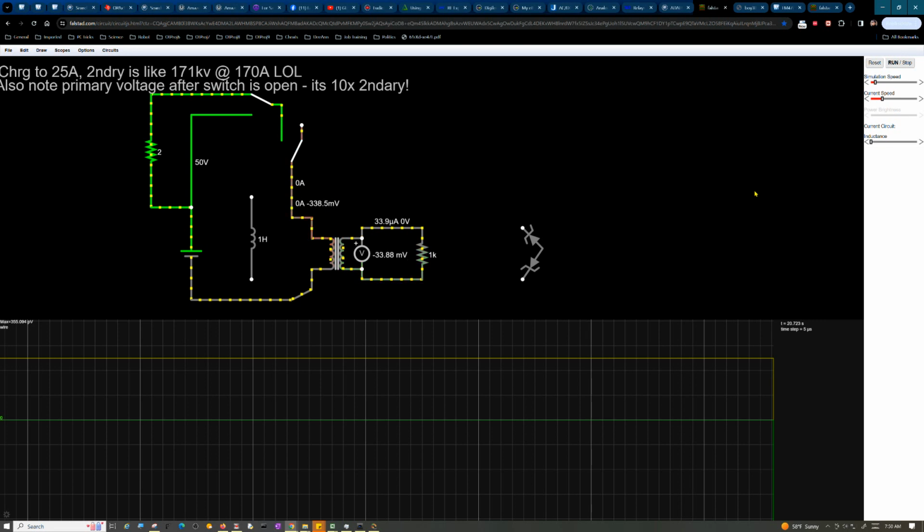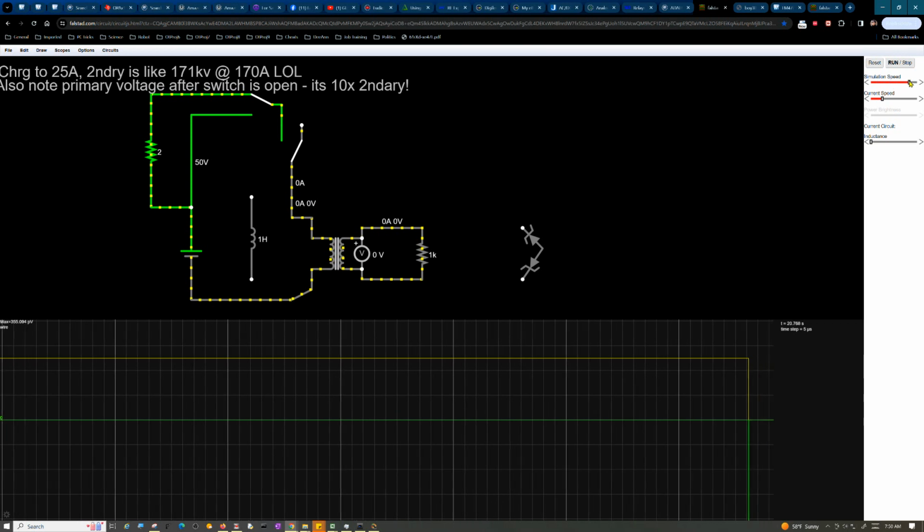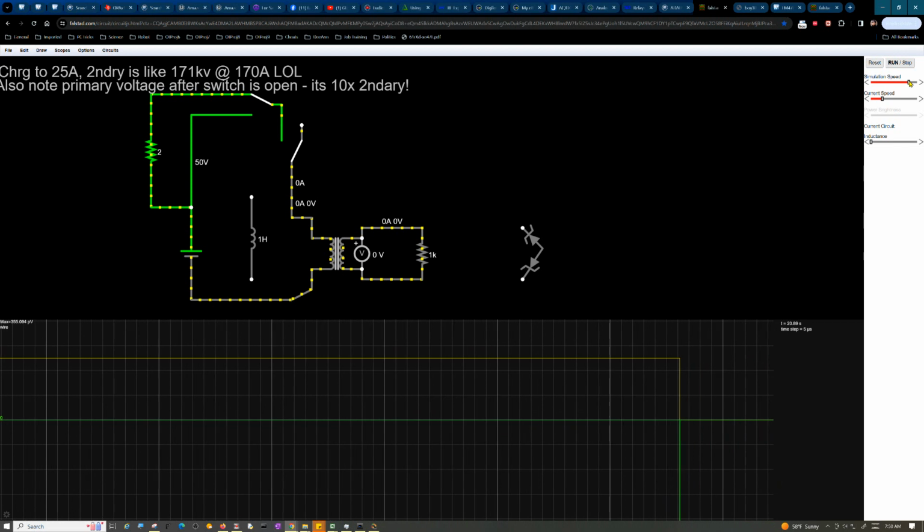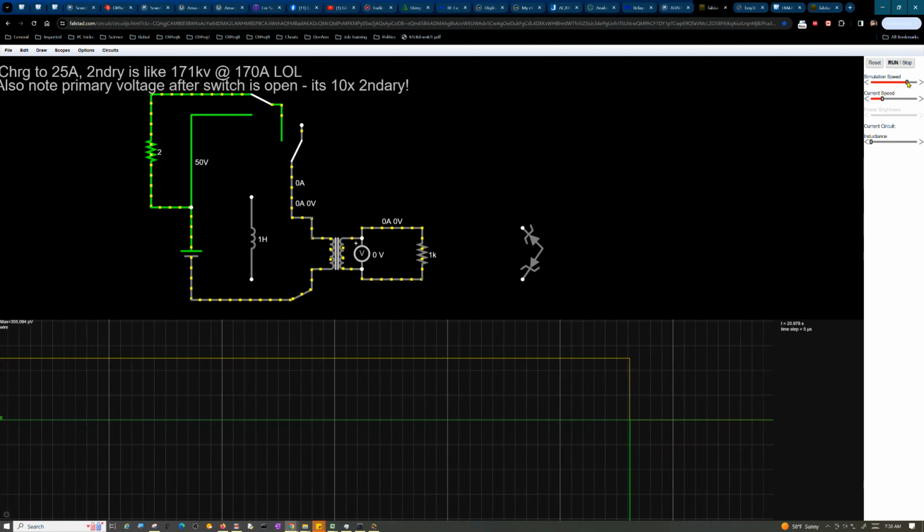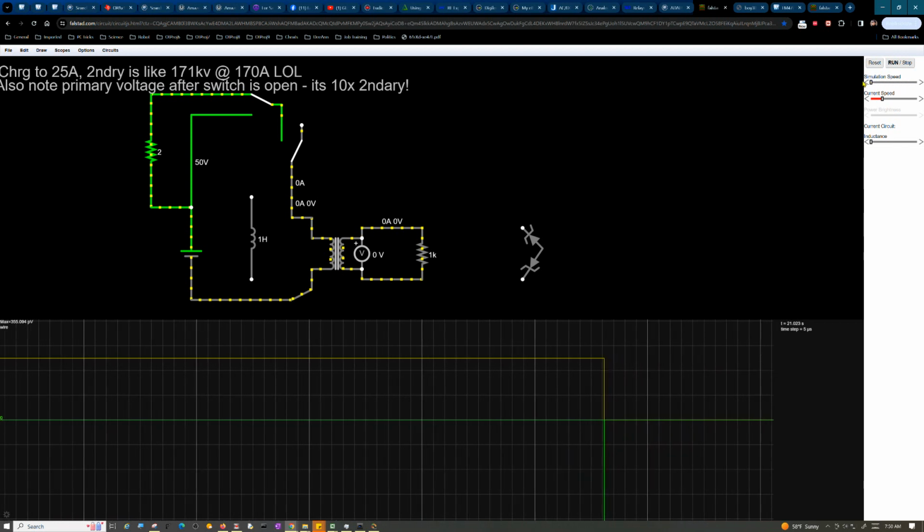Saw that, 74 kilovolts, right? And this happened in such a quick flash, even in slow motion, I didn't catch it. It just happened super duper fast because of how much voltage it's generating. Earlier I had these two back-to-back TVS diodes, which is how I initially did this test, and of course that keeps the voltage more constrained. I'll put those in play here in a second.